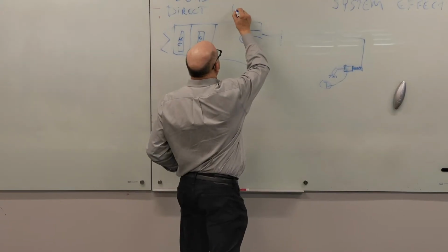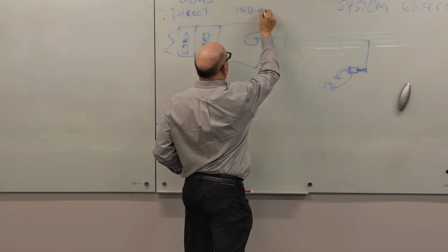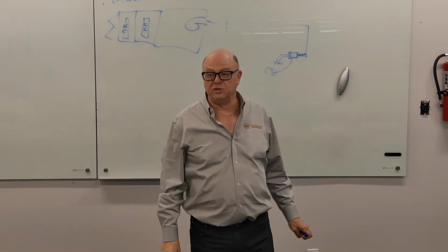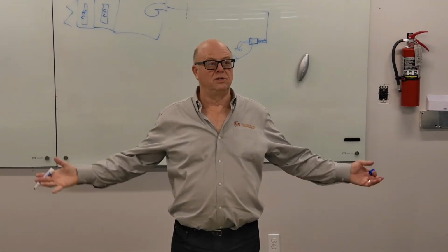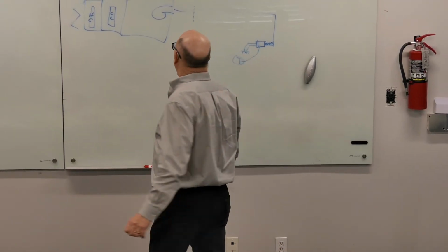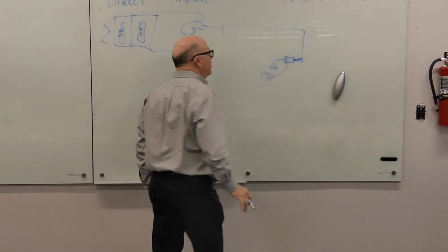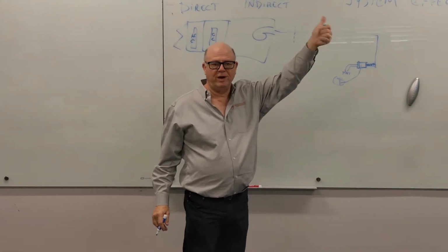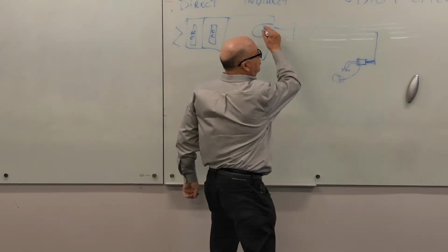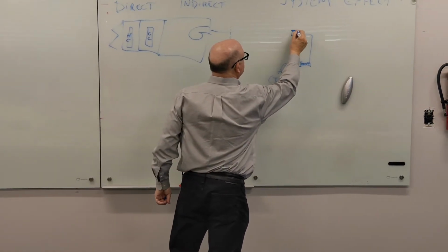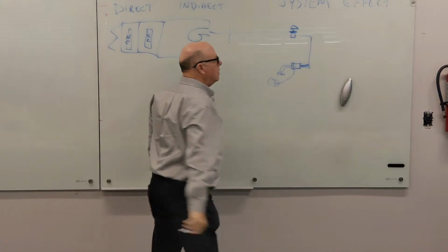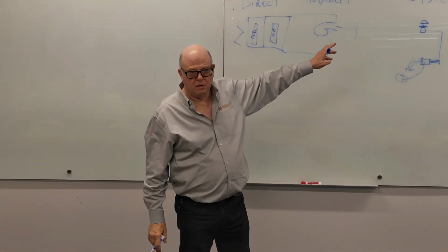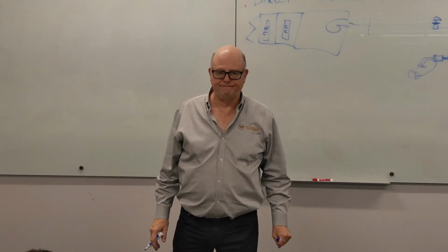What we do instead is we use an indirect method. What indirect method do we use to tell that fan how fast to go? Somebody say duct pressure, thank you. There you go. The conventional idea, you know, wives' tale conventional item, is you go 2/3 of the way down the duct and you put a little pressure sensor here. And that pressure sensor is set for some number.